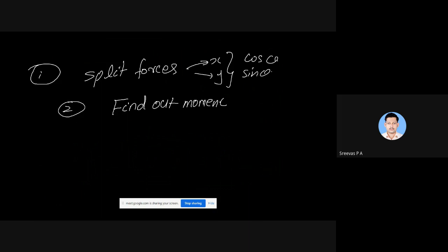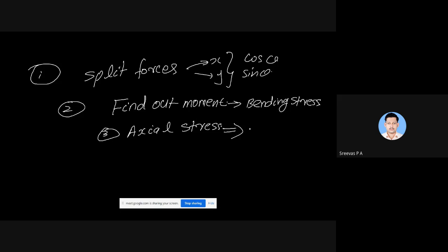Respective distances are mentioned in the question. After finding the moment, find out bending stress. Axial stress also will be there. Then find out net stress.